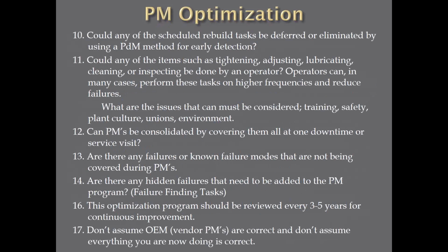Number 11, very important. Could any of the items such as tightening, adjusting, lubricating, cleaning, or inspecting be done by an operator? It says operators can, in many cases, perform these tasks on higher frequencies and reduce failures. A lot of times people say, well, my operators can't do that. They're not smart enough to do that. We can't trust them. Again, those are issues you have to work around.